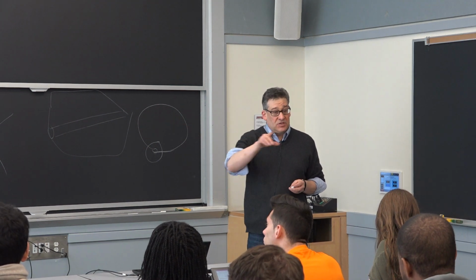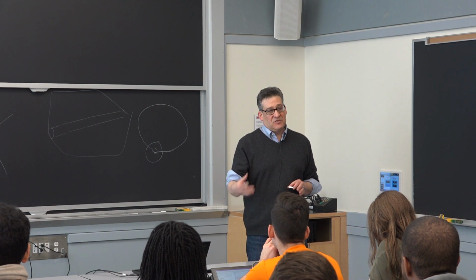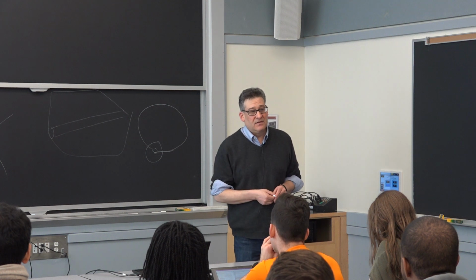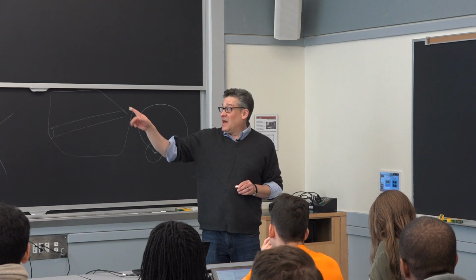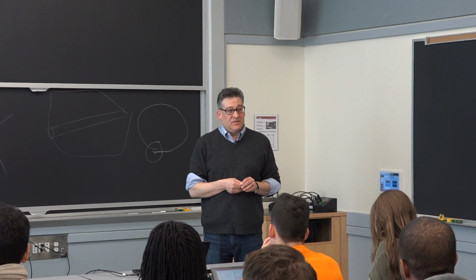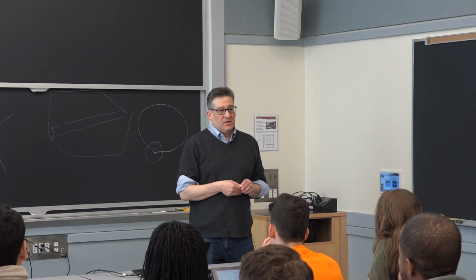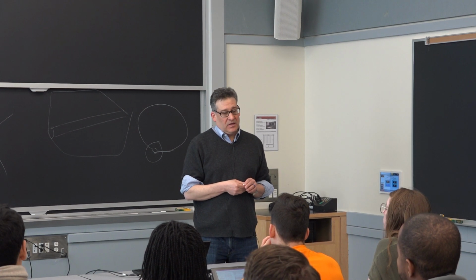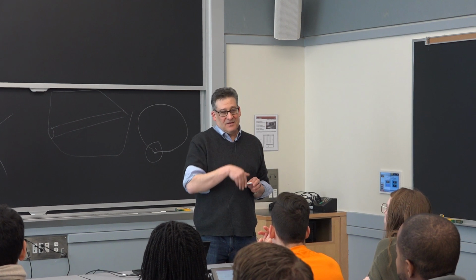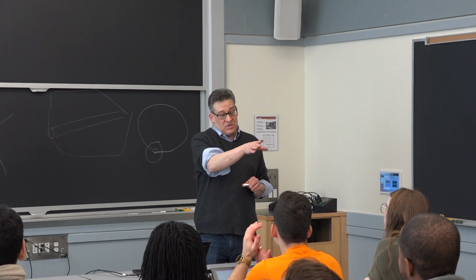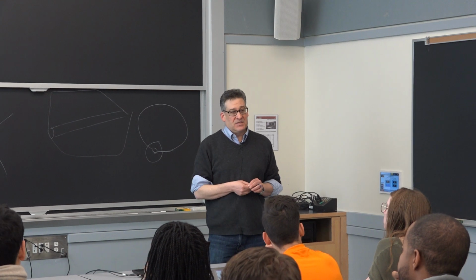But to Matt's point, though, this is exactly what I've shown you. How do you design? This is your design for stiffness scenario. When you're talking about this dynamic loading and what inputs are going to the body and what's the natural frequency, that's the same thing as saying stiffness. So you want to keep going stiffer and stiffer and stiffer, right? So that makes sense. Then you begin using those design for stiffness things. And that's the place where you'll never win out with steel, except for tensile loading, right? But with bending, torsion, buckling, that's the place where you start doing better with aluminum, like I said. And this is where you start using exactly what I've shown you, is how not to get into those resonant frequencies, how to stay away from those resonant frequencies.